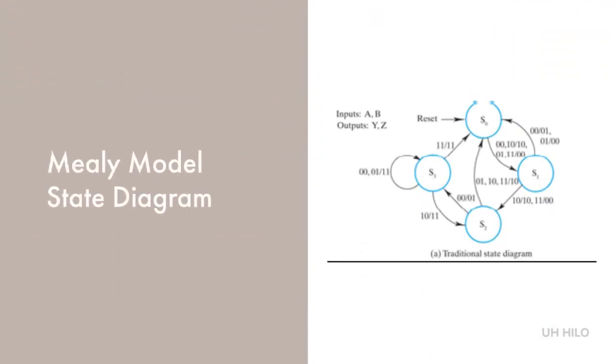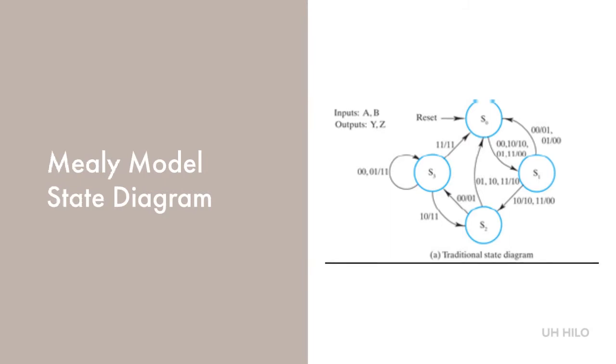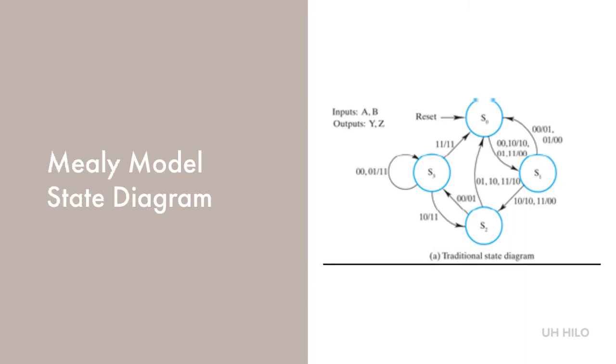Although this model serves well for very small designs, it often becomes cumbersome or unworkable for large designs. In particular, all 2^n combinations of input variables must be represented on the transitions from each of the states, even though the next state or output may be affected by only one of the n input variables. The output variables can also present problems. For each state or input combination label, up to 2^m output combinations must be specified, though only one among the m output variables is affected by the state and input values.